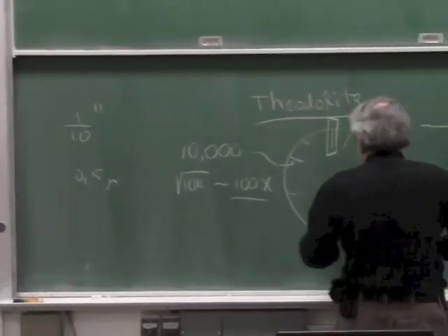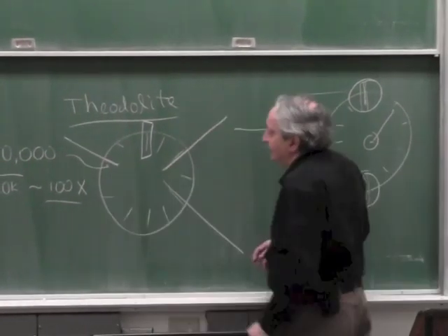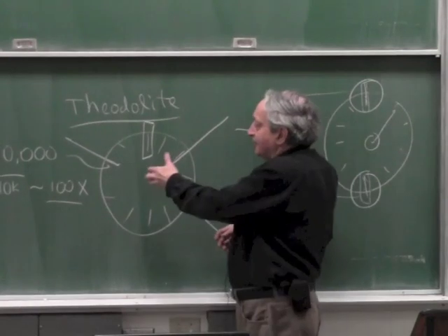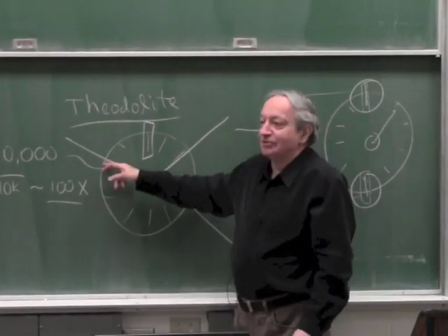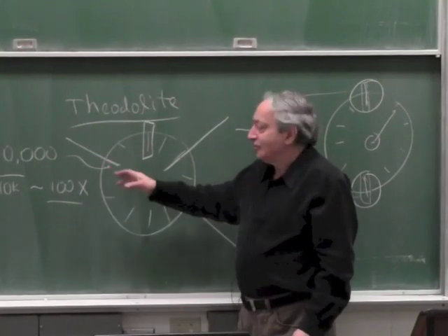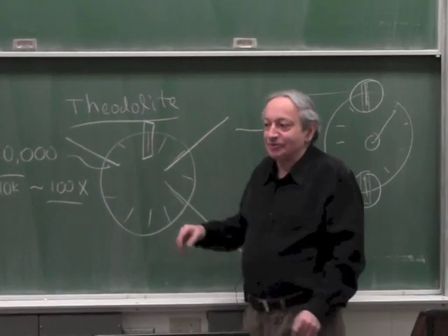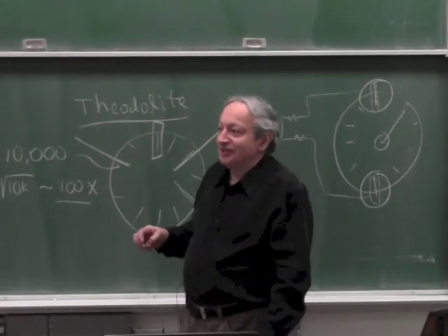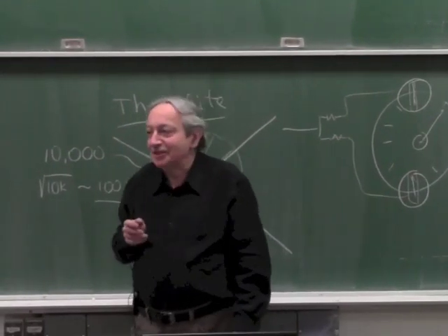And therefore, again, what he did, if this was the wheel, he put microscopes at random positions which aligned. So you have 3 microscopes at random positions. And now, if you rotate the wheel, if it's perfect, if one microscope lines up, the other 2 will line up. If it's not, you have to file the gears until eventually, at any position, the microscope will line up. And using this and 6 months of patience, he achieved better than 1 arc second 200 years ago.